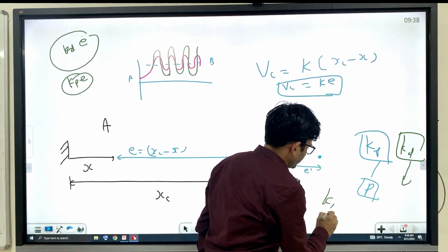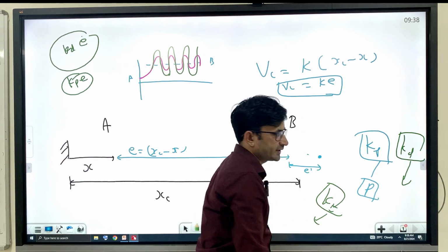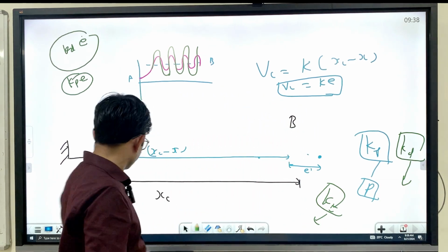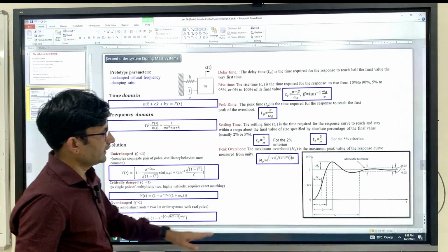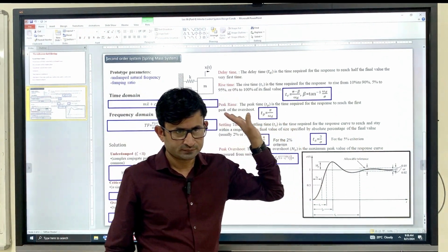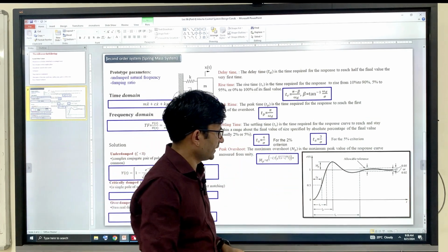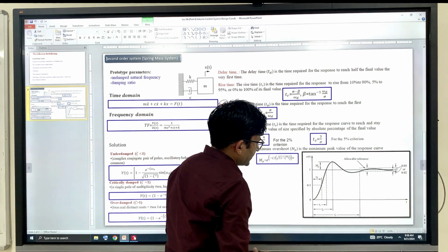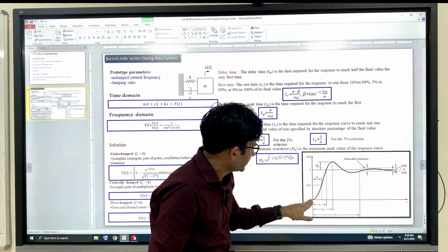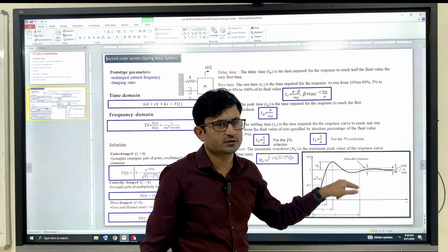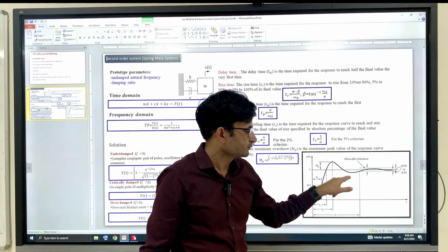And Ki is used for eliminating the steady state error. So you can see from this diagram, let's say I have this kind of response. Now if you want to control this, let's say this is the closed loop controlled response. Now the Kp is responsible for reaching from 0 to 1, but with oscillation we have seen, right?